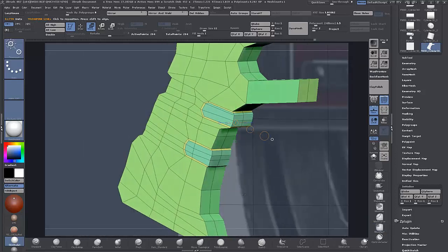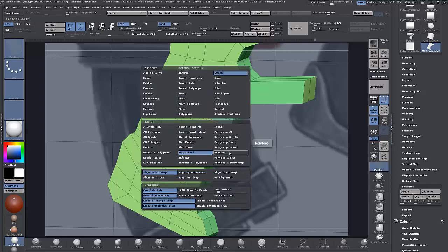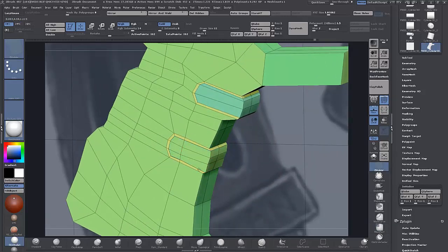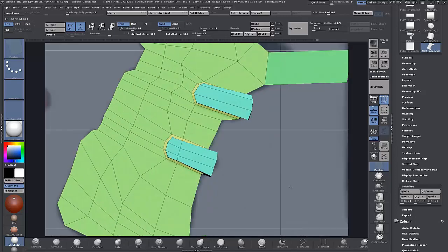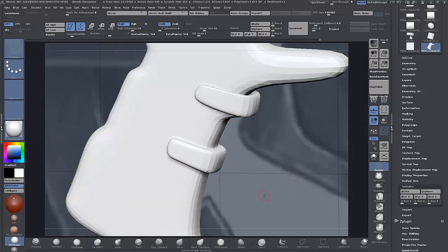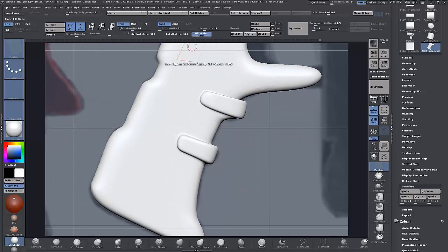So just clear your mask. We have a polygroup island there, so back to the Zmodeler-Zbrush and QMesh polygroup island, and we'll just come out once, and then you can tap Alt to change the polygroup color, and then just click up here to repeat that. I just want to check that now for a second, and I'm just going to set the subdivs here to 4, and I just want to check in fill mode.